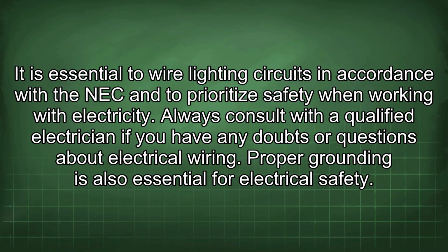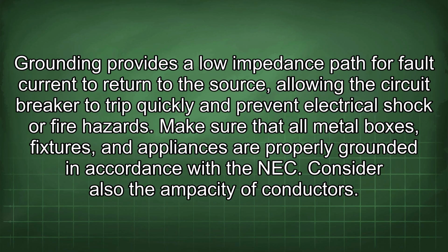Proper grounding is also essential for electrical safety. Grounding provides a low impedance path for fault current to return to the source, allowing the circuit breaker to trip quickly and prevent electrical shock or fire hazards. Make sure that all metal boxes, fixtures, and appliances are properly grounded in accordance with the NEC.